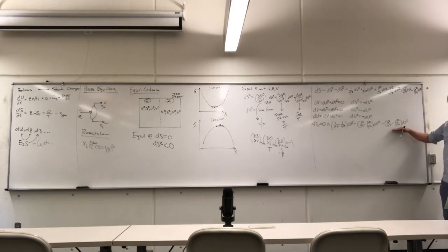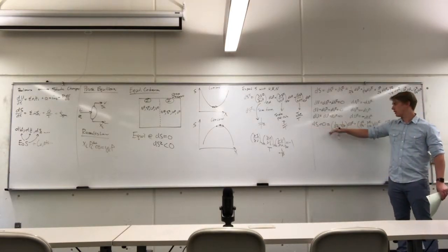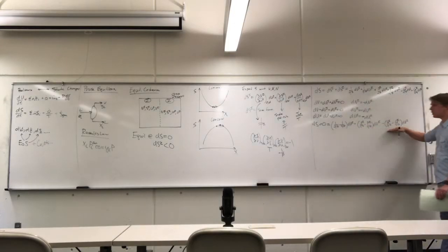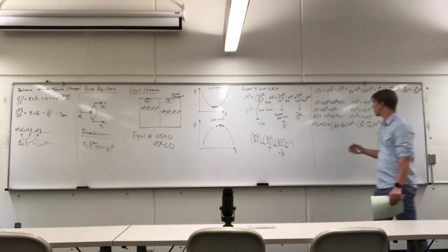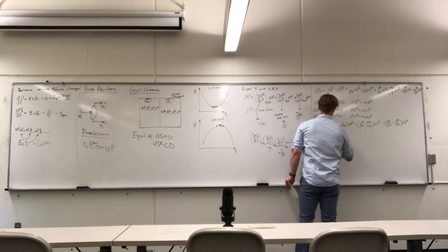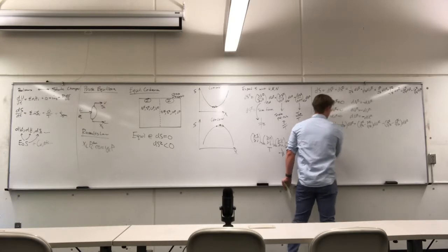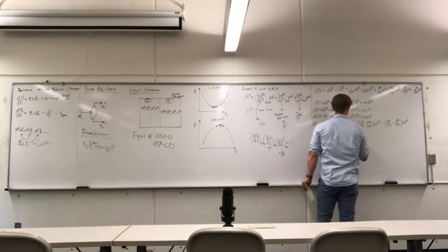So the only unbiased way that we can be 100% positive that the rate of change in entropy is always going to be 0 is if each of these 3 terms are all 0 independently. And from this we derive 3 criteria for equilibrium. Criteria 1 is thermal equilibrium. In order for these 2 chambers to be truly in equilibrium, their temperatures must be exactly the same.